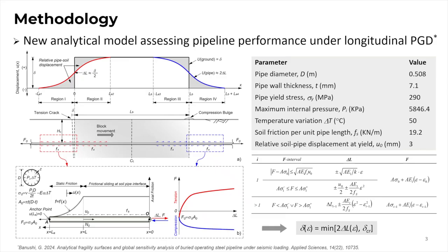The magnitude of the total pipeline displacement in tension and compression is equal to the ground displacement delta until the soil friction mobilizes over the entire soil block in case 2, remaining constant thereafter, that is case 1. This allows us to directly assess the amount of ground displacement delta that induces a maximum pipeline strain, either in tension or compression, at the soil block head and toe, respectively.